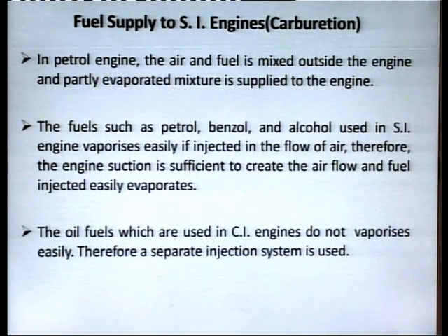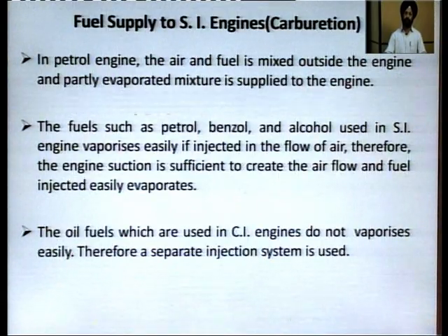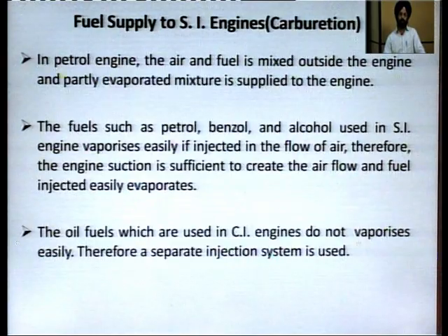Another most important function is atomizing and vaporizing of the fuel in the carburetor. This is done by injecting the fuel into the air coming through the venturi, which we will discuss after we know the construction.